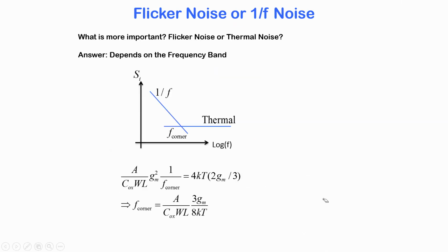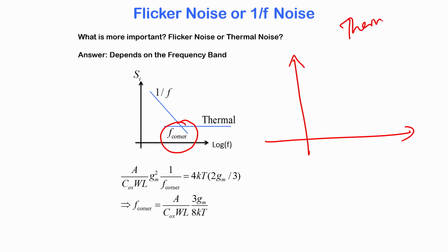And finally, the very last topic has to do with something called the corner frequency with regard to noise in a MOSFET. And what is corner frequency? We know that in a MOSFET there are two key components of noise. We have the thermal noise and we have the flicker noise. And thermal noise is rather frequency independent, it is almost constant at all frequencies, and therefore it is called white because it has all frequencies in it. But flicker noise has a 1/f dependence. So, it is very strong at low frequencies and very small at high frequencies.